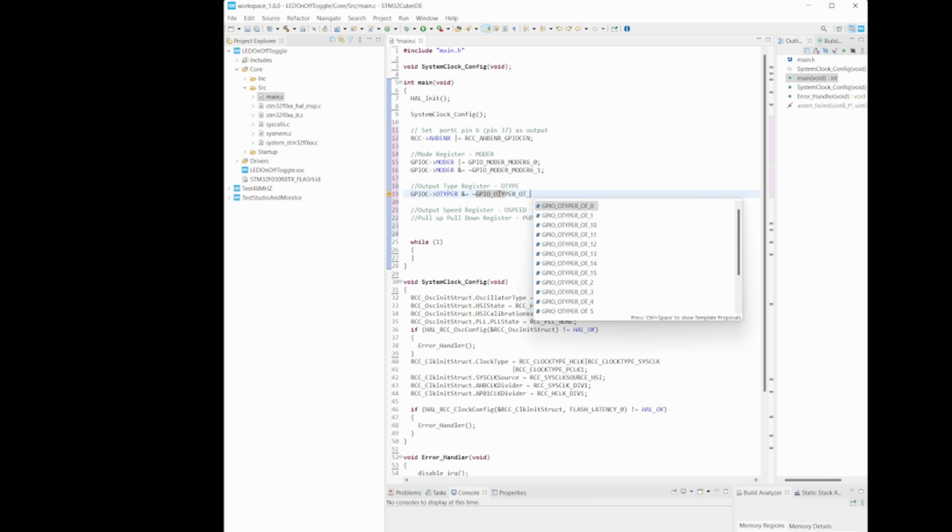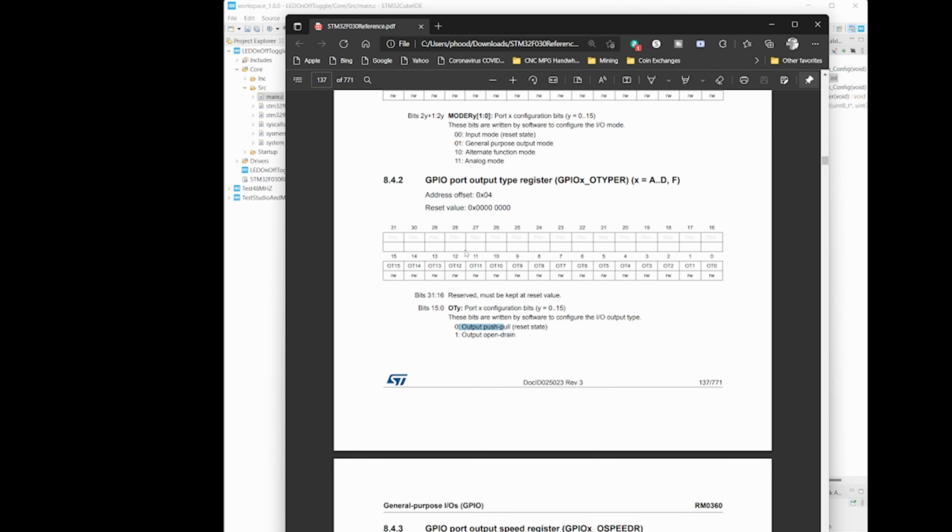And we're going to use the Control Space again to go to the one we need. And since this is actually showing you only a single bit, let me show you why that's happening. You can see that even though this is a 32-bit register, you're only using from 0 to 15, which is 16 bits. All of these other ones are reserved. So we're only needing to either put a 0 or a 1 for that particular pin. So that's why it only needs 16 bits.